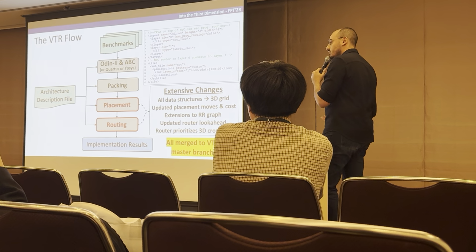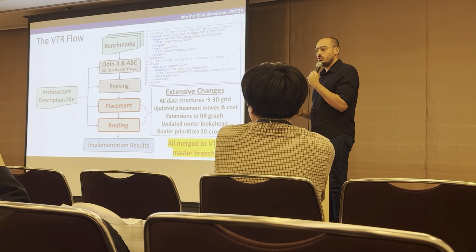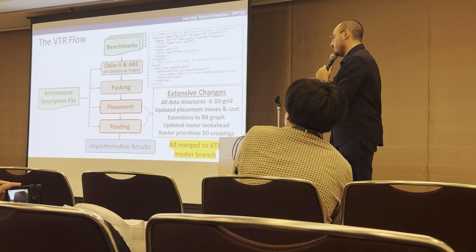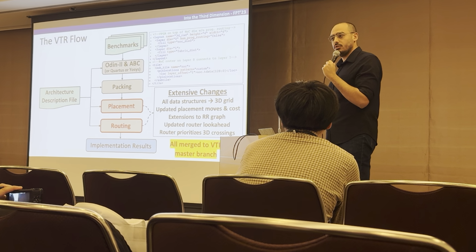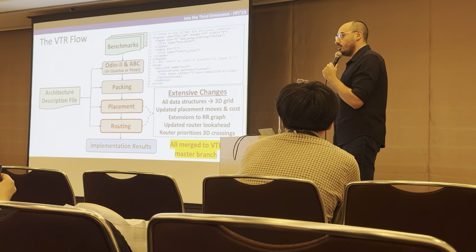So all those changes that we do to VTR are merged to the VTR master branch, so any future development on VTR will build on top of those changes. That's why we made sure that those changes have no effect on the quality of results and minimal effect on runtime if you want to do experiments on 2D conventional FPGAs.